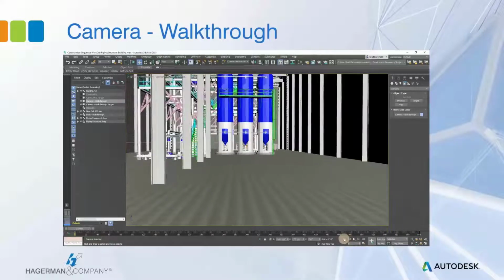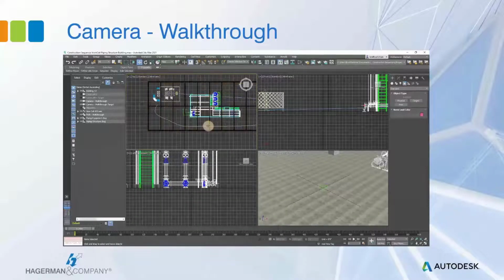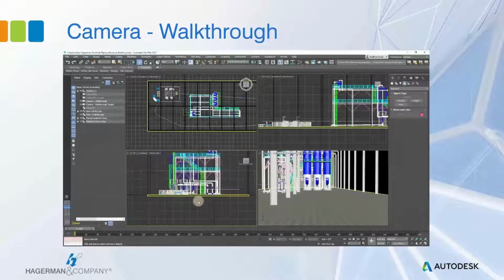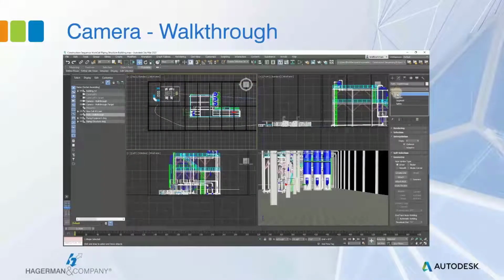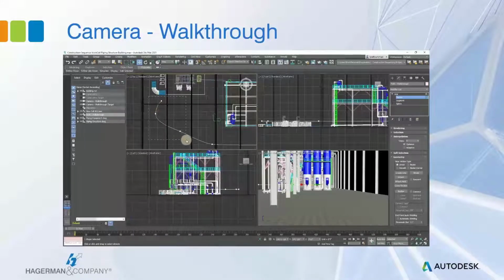The next thing we're going to do is change the last couple of points. We're going to give the camera a little more behavior here. This is not bad, but I think we can do better. So I'm going to switch to all 4 viewports here with my viewport layout. And I'm just going to elevate the last couple of points on that path. So I'm going to go back into vertex mode. Go back to the modify panel. And then vertex. And then I'm going to select those last 3 vertices and raise them up.